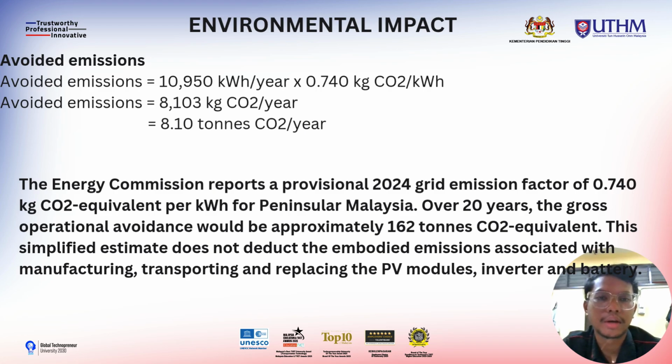For the environmental impact, avoided emission: 10,950 kilowatt hours per year times 0.740 kilogram CO2 per kilowatt hour equals 8,103 kilograms CO2 per year, or 8.10 tons CO2 per year.